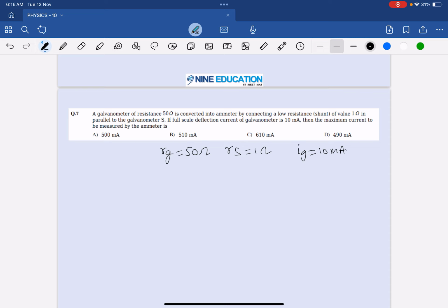You know that a galvanometer is basically something that only decides in which direction current is going. It does not measure, it is used only for detecting very small currents. So here we are adding a shunt resistor to a galvanometer. Now this galvanometer says that please do not give me more current. So we are giving some current I, Ig will go here and I minus Ig will go here. Now this is my shunt resistance, this is the resistance of the galvanometer.